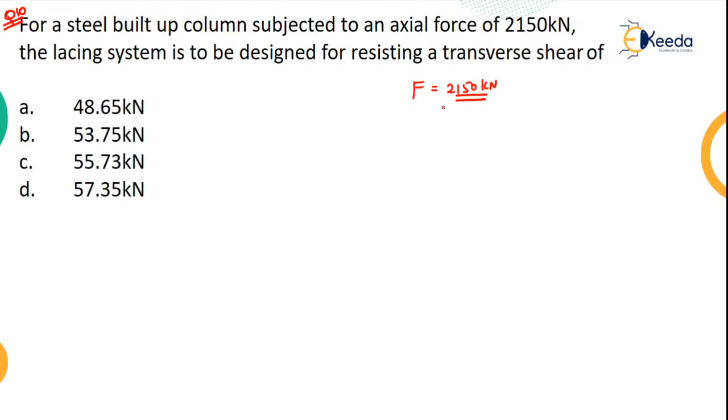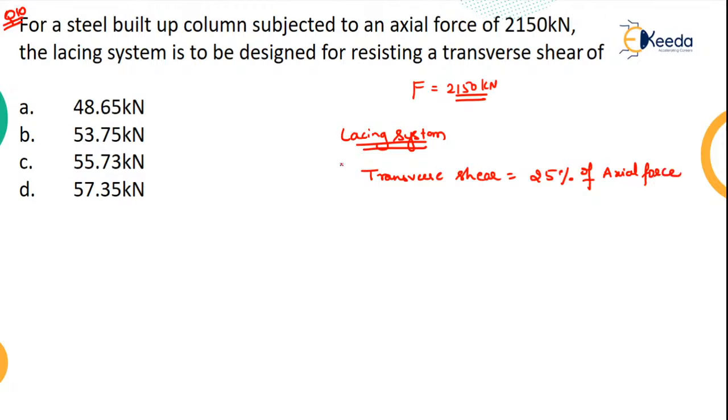So it's asking you to calculate the transverse shear in case of lacing system. Okay. So if you go for lacing system, your transverse shear is equal to 25% of your axial force. Very simple. This is a standard which you have to remember. Right.